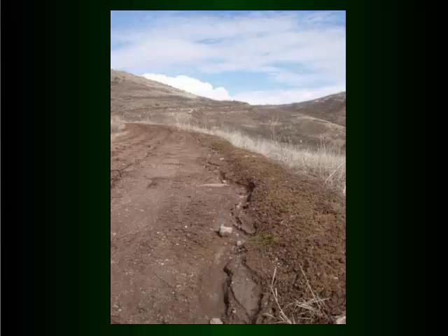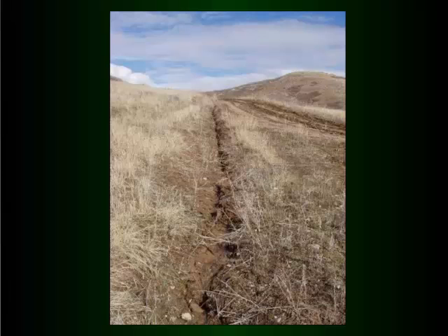Situation where you've got a little bit of a berm on the outside of the road, and you can see instead of allowing the water to go off the road, it's trapped, it's containing it, and it's got enough energy there to cut that surface. So that means that's probably an annual event in that case to go in there and regroom your road. Ditch line carrying too much water and cutting. Another situation where you probably need to, with pipes or water bars somewhere up the hill, get rid of some of that volume of water.